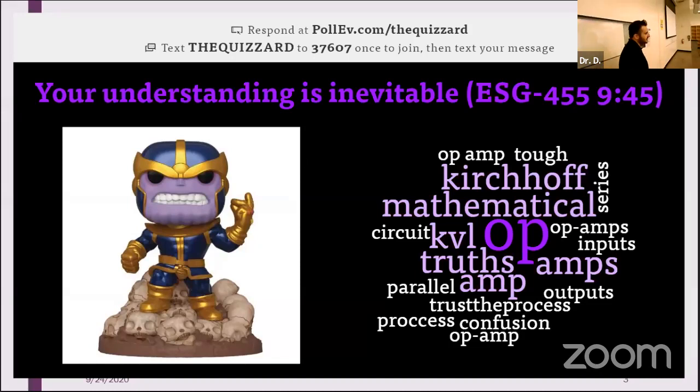And why do we want to do that? Just so we don't have to handle all the different voltage drops and things like that, right? We can solidify one voltage drop across all of our elements. And if we had one equivalent resistor of this size, we would get the same response, right? That's the whole point of bringing things together. Parallel are when the paths are parallel, and series are when they're connected in line, right?